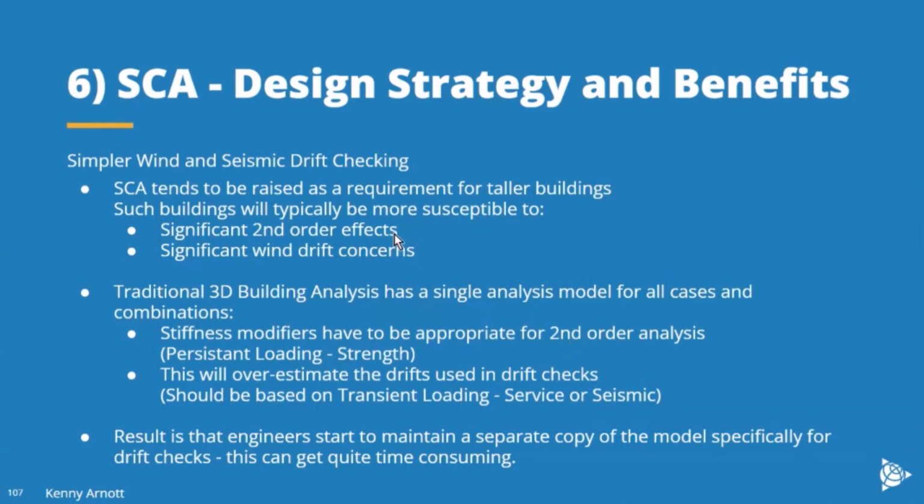So the safer thing to do is to make them appropriate for the second order analysis, which means that you will overestimate the drifts. The adjustments for the drift checks should be based on what I've talked about as a transient loading level. I talked about that, I think, in webinar 4.